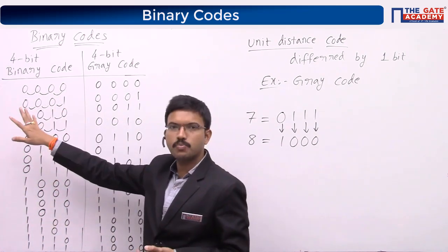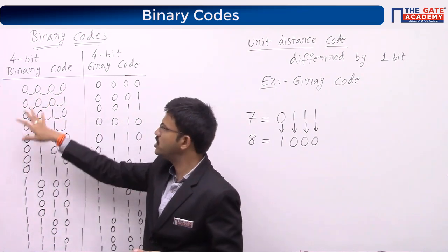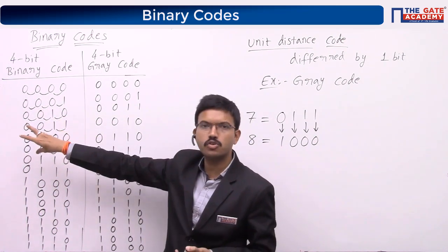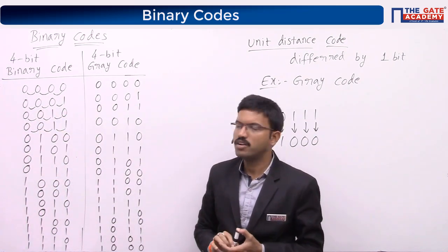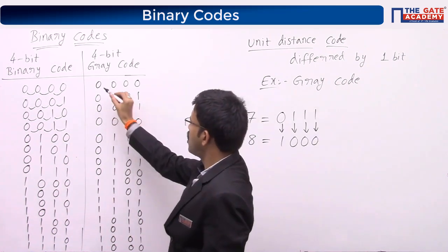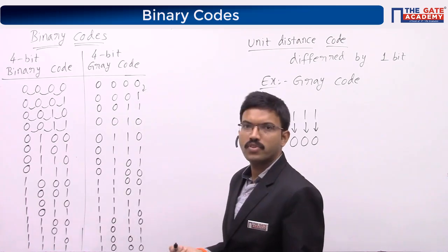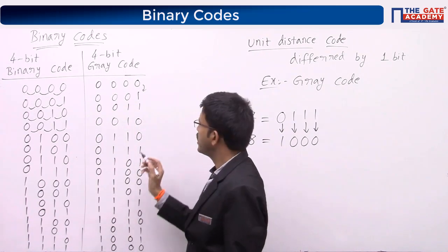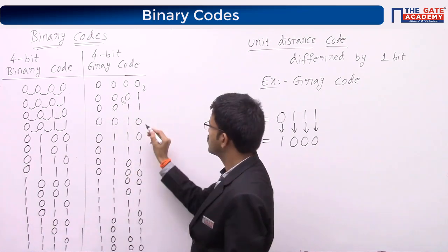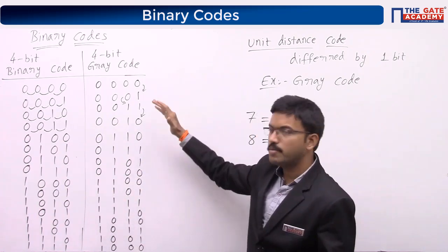Okay, so corresponding to those digits we have the code like this. This particular code is called sequential because if you consider any two successive codes, the difference will be 1. Now let us observe this particular gray code. Just observe, here all the bits are zeros. Here only this bit is changing, 0 to 1. Remaining 3 bits are same. Next, here only this bit is changing, remaining bits are same. Next, this bit is changing. Like that, you just observe this particular tabular form.